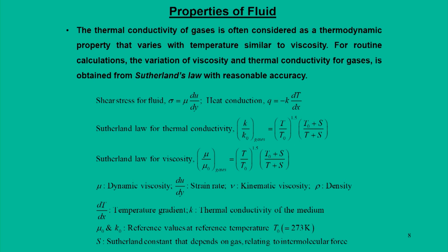Now, to address these changes, what has been proposed in this gas dynamics course is a term called Sutherland's law for viscosity. It has been seen, with reasonable experimental validation, that thermal conductivity and viscosity are vital parameters and are mostly dependent on temperature. So, during a fluid flow, if the temperature change is significant, then it is very likely that viscosity and thermal conductivity are going to change.